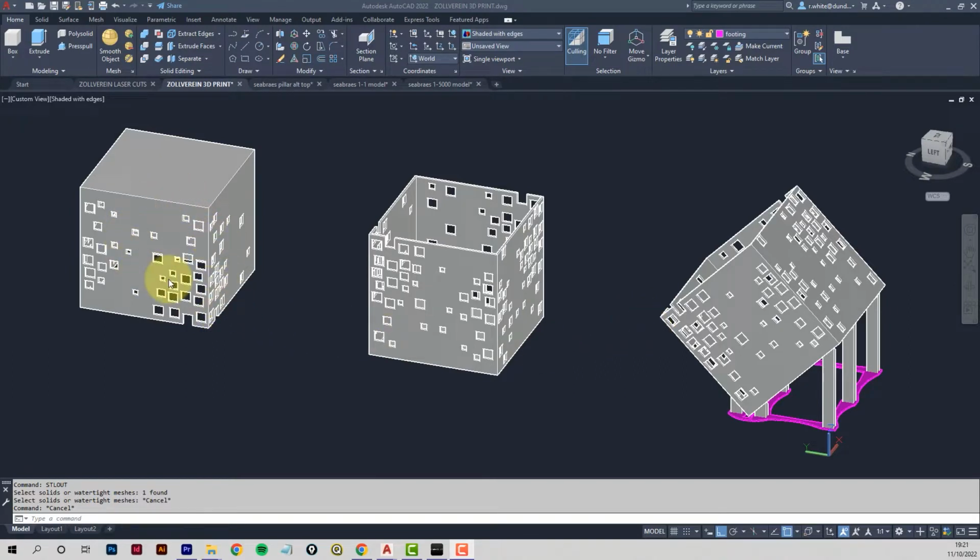But this is going to be pretty obvious what happens here. This form is going to require a lot of scaffolding because there's a big roof and nothing else inside. It requires a fair bit of scaffolding, notably in all the window openings, because they're just a little too big to bridge across. The 3D printer can't just throw a line across these. But if you tilt the whole model at 45 degrees, it eliminates the scaffolding, providing you put in some support, because it's inherently likely to fall over because it's heavier on this side because of the roof. There's no roof on this side.